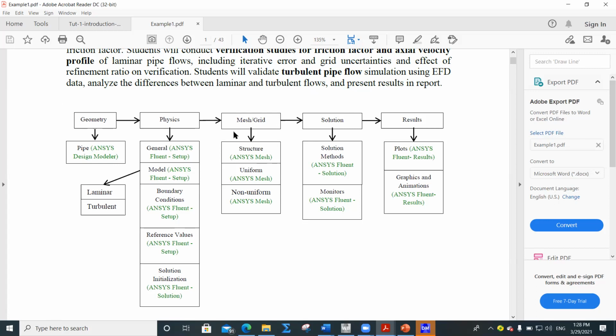Okay, and for this problem, there is the so-called Y plus definition. The Y plus is a non-dimensional unit that correlates the flow velocity and the farthest layer of the grid near the wall, the distance delta y. When this parameter, the y plus, is much less, this means that you model your boundary layer much better inside the boundary layer.